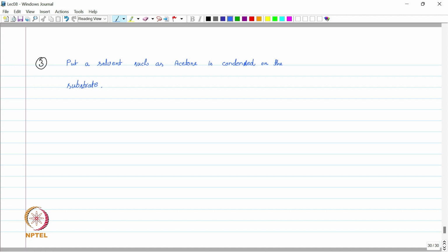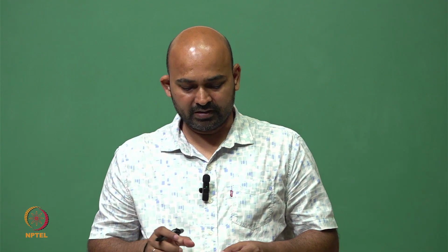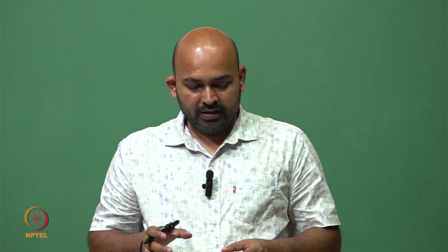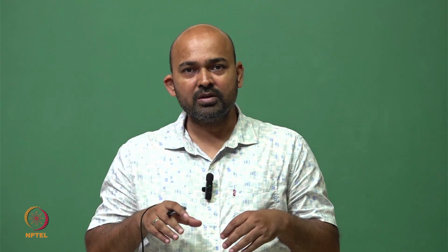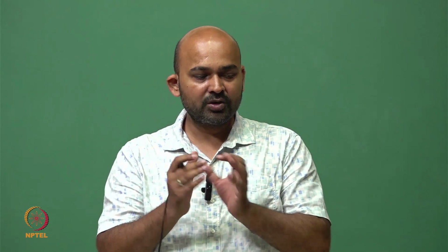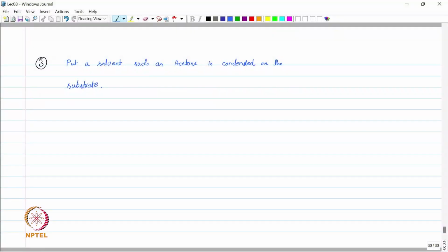So in this step, we take this condensed liquid, which can be acetone or some other glue. This acetone is poured on this structure, on this forest of CNTs. When we pour this acetone, all the CNTs will stick to each other, and due to the capillary rise, the solvent is actually drawn into this forest of CNT independently. So if we draw this step now, we have this wafer.